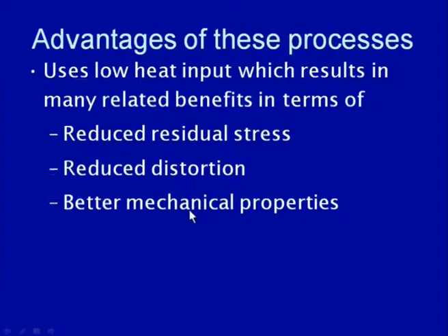The hardening of the base material leads to cracking tendency, while the softening deteriorates the mechanical performance, that is, the ability to take up external load. That happens mainly because the excessive application of heat during fusion welding processes leads to significant change in the microstructure and mechanical properties of the heat affected zone.